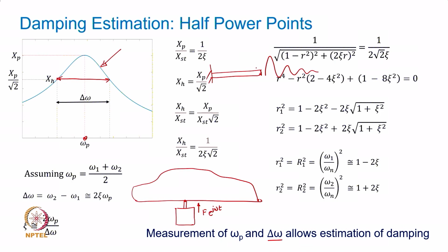You could simply put an accelerometer here and generate that response, but then it applies to simpler and smaller systems well. Many times you need to excite it, so people use an impact hammer or a small gentle tap. So, you can't do that with bigger systems.